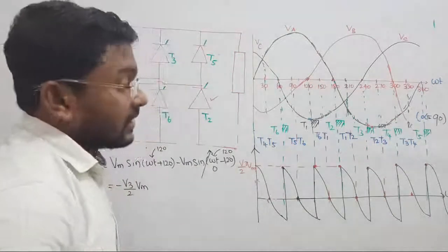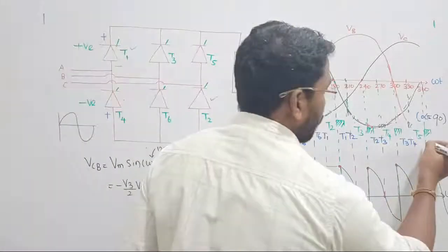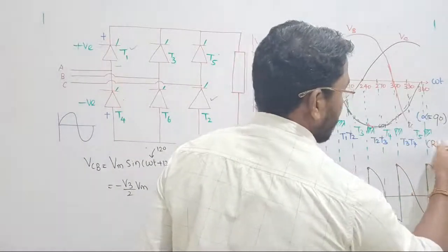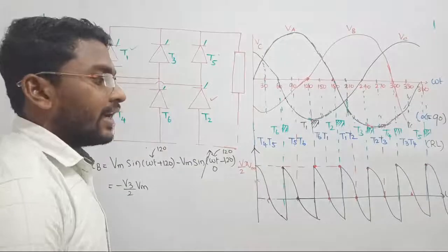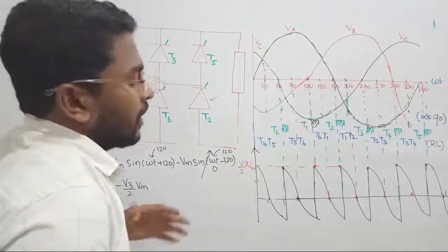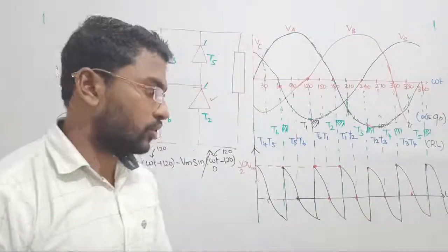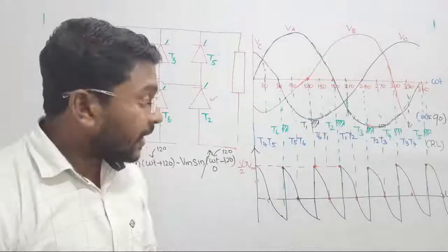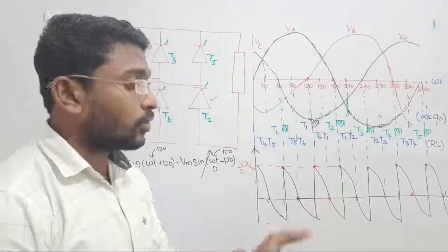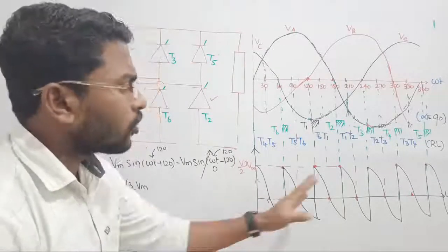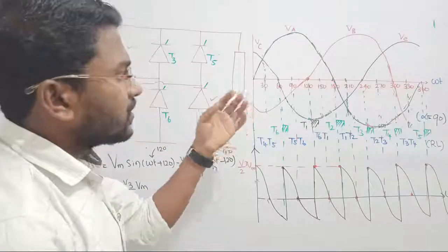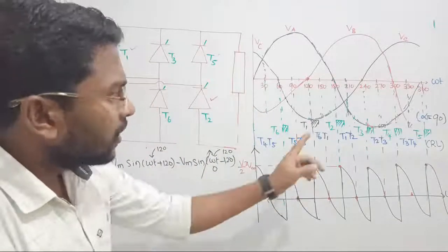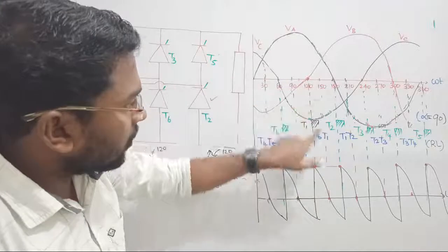But this negative waveform is possible only if I have RL load, exactly, an inductive type of load. If you have an inductive type of load, then we can happily let the negative spike also appear at the output port. Suppose you don't have the negative spike, then what will I do? I cannot go beyond this. See there, if it is the resistive load, right, we are triggering the thyristor at, where will we trigger?